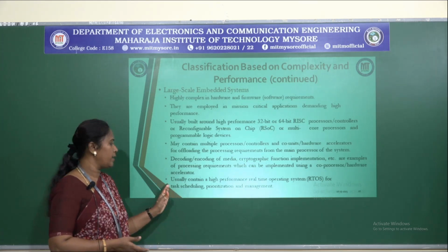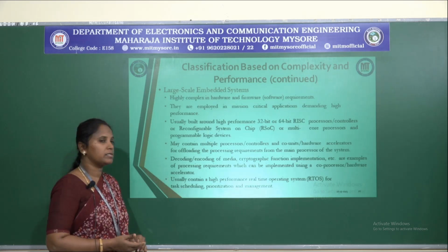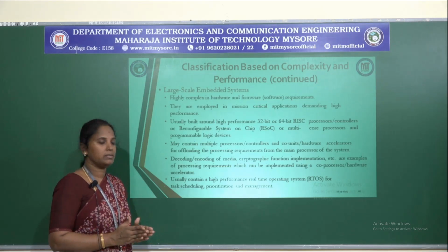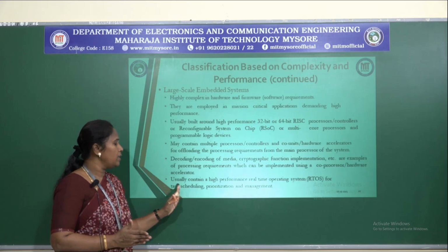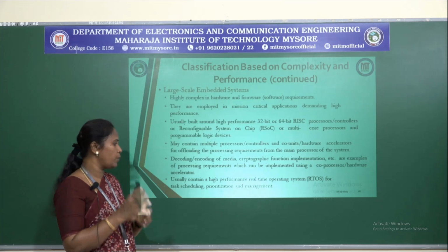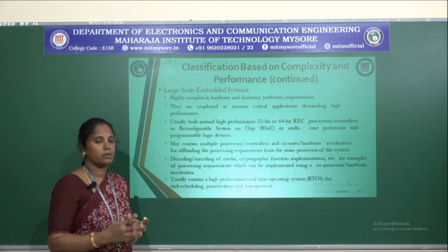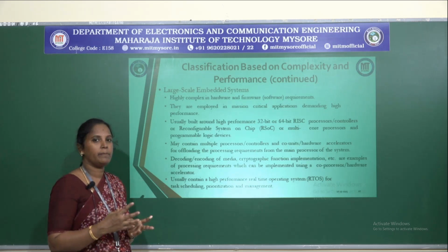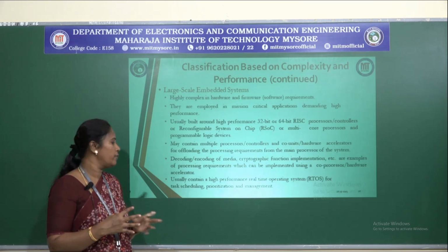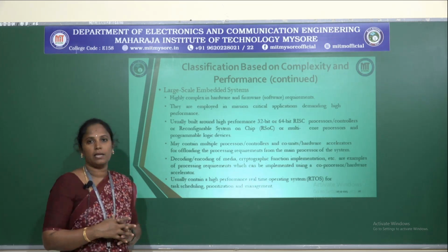And also here a high performance real time operating system was used, because the task has to be done within the specified time, and you can have task scheduling, that means which task has to be completed by what time, and also the priority, that is, among numerous tasks which task has been given the first priority. All the management of those priority levels as well as the assigning of task scheduling was done in this large scale embedded system.